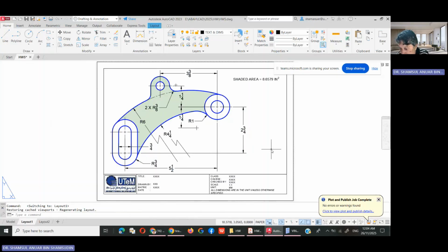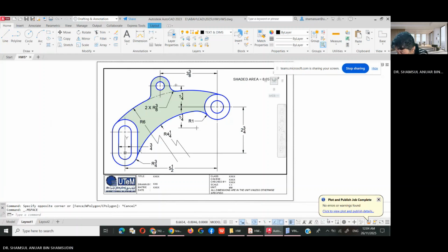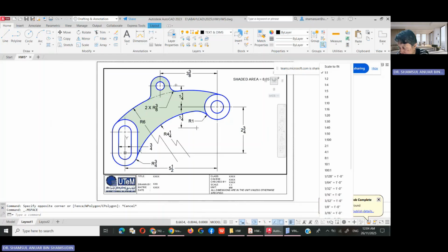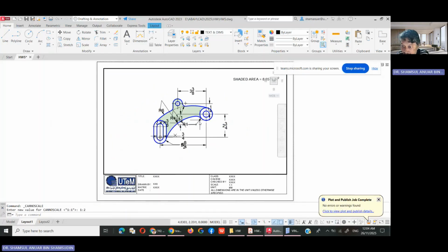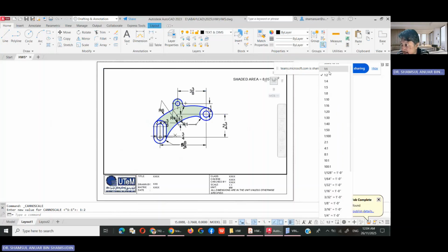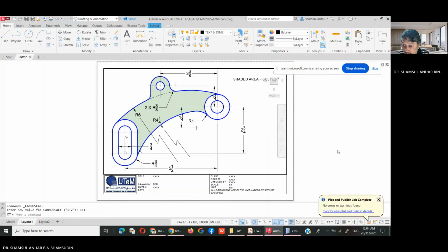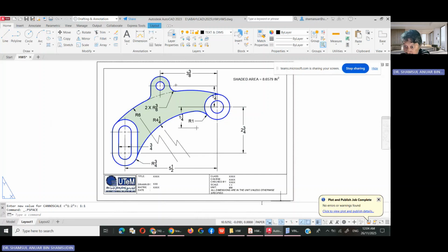And again, check the scale is correct. So this is the maximizer. So if you go to 1/2, everything else will follow, but it's not going to be that cool. So that is not maximized because you have a lot of empty space. So you want to go maximize, but within what is commonly available. All right. So when you're done, you can click back on the paper space.